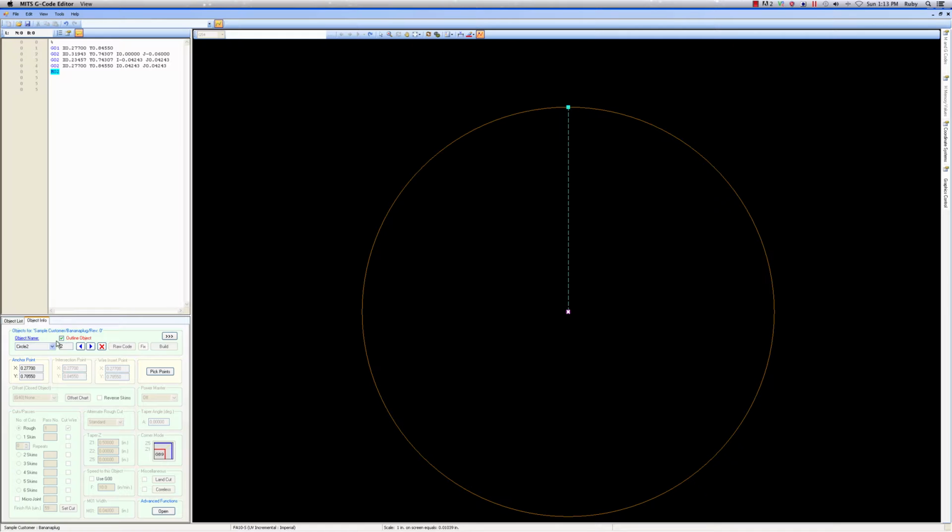First of all, we take off the outline object and we will give it a new name. We will call it R0.06 and save. Our anchor point, intersection point, and wire insert are automatic on a circle. To change them, you pick points.